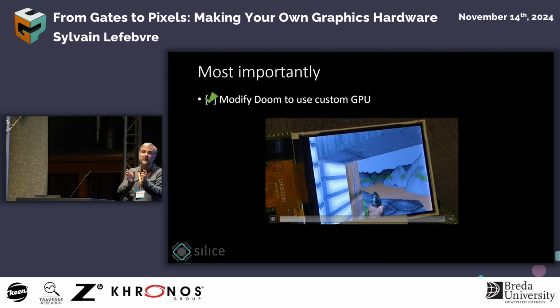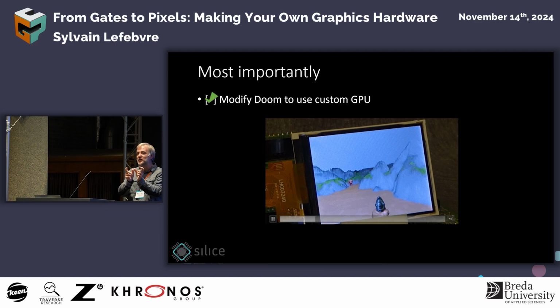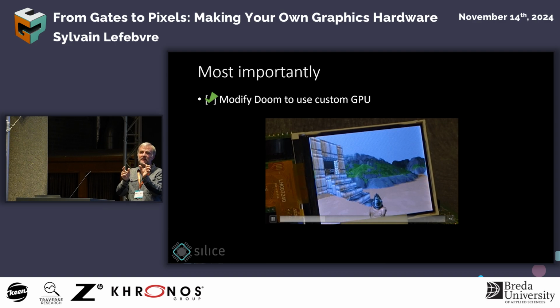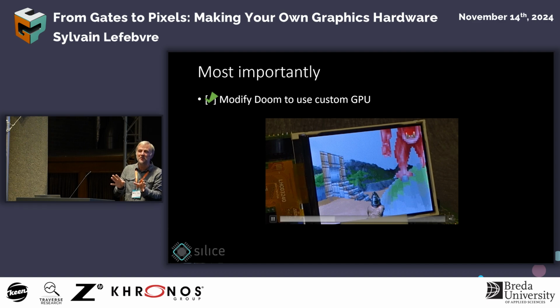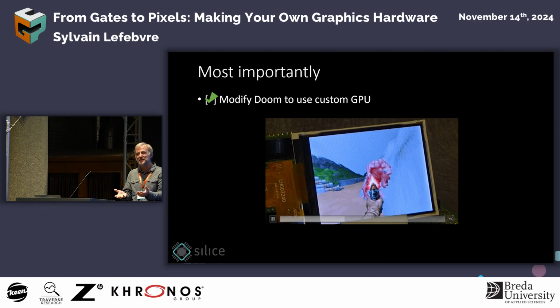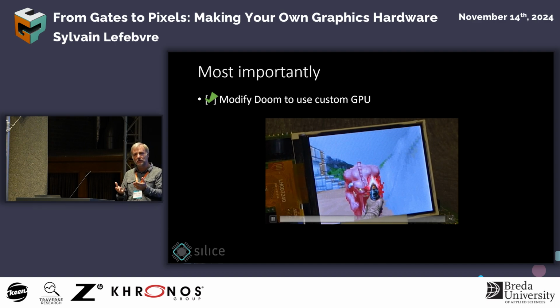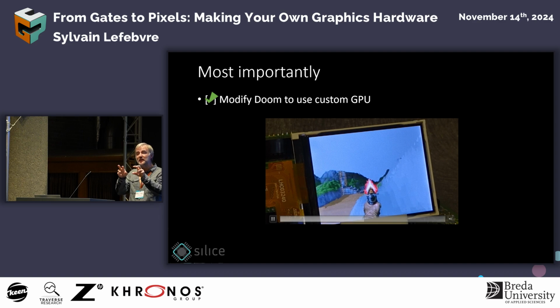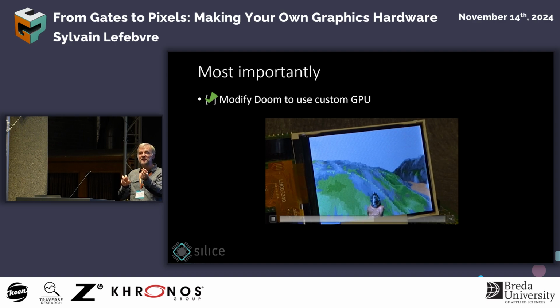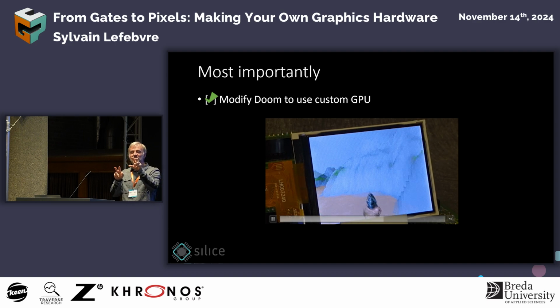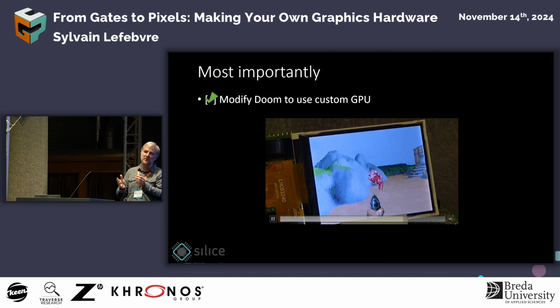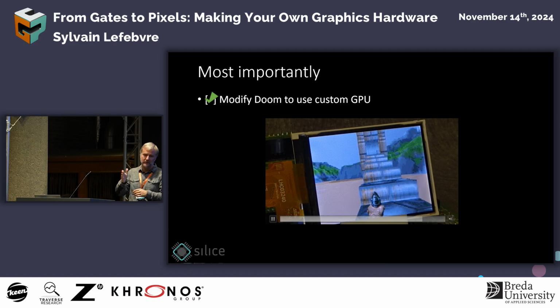And it's very tricky because at 100 megahertz, if it's a bit less than the optimal placement, it's not gonna work, right? So the way I've seen people go around this is by manually placing parts of the design, specifying where some of the logic has to go on the chip, and I haven't tried that yet. But I know it's possible to double the speed of the memory controller, which would already go a long way.